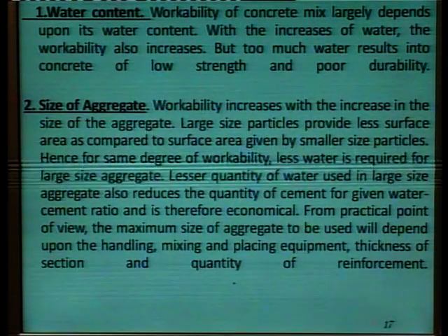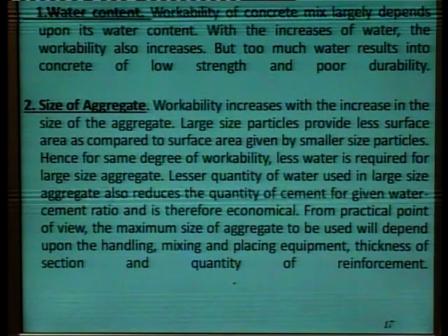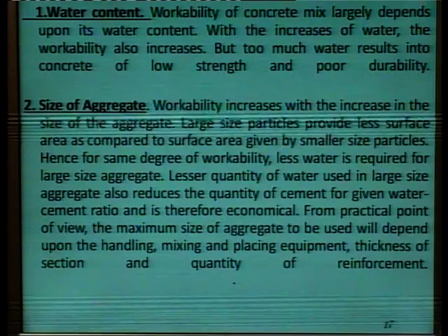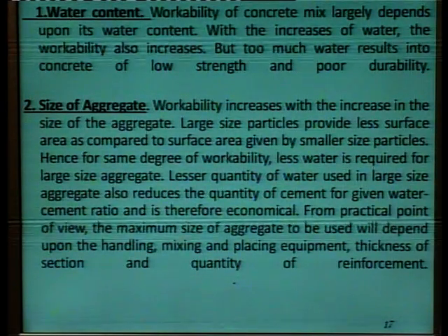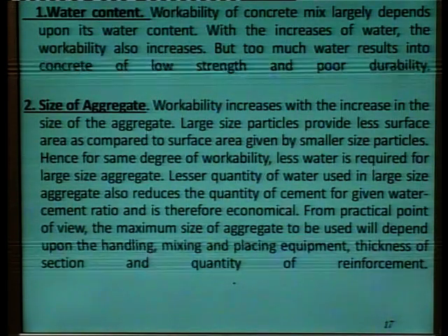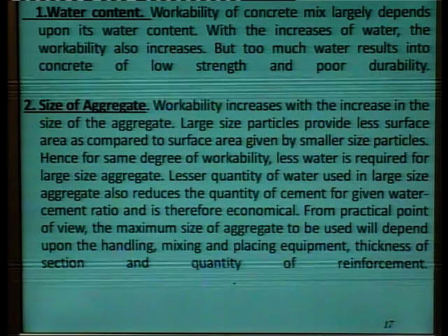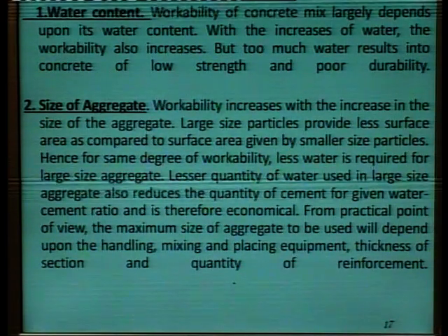Workability increases with the increase in the size of aggregate. Large size particles provide less surface area as compared to the surface area given by smaller size particles.